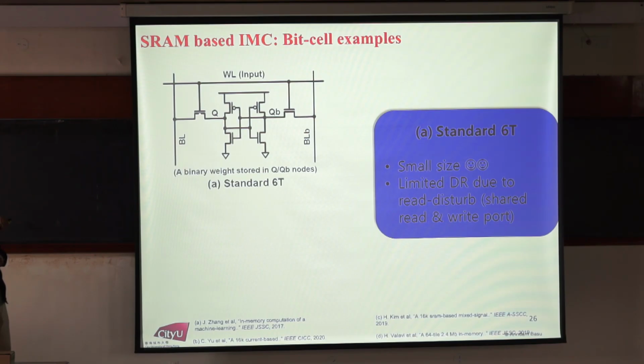And this transistor will now actually start writing current into the cell. So what happens, this is called a read disturb. As a result of your read operation, because there are many cells getting enabled together, some of the on cells can actually write data into the off cell, turn it on. Okay, so that's a big problem with SRAM based IMC.